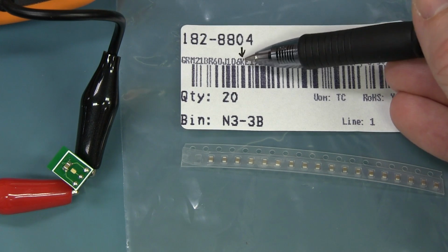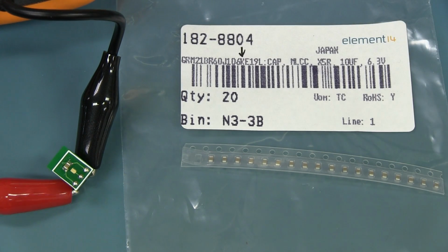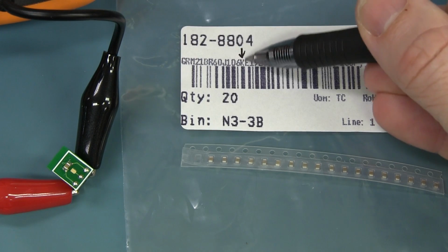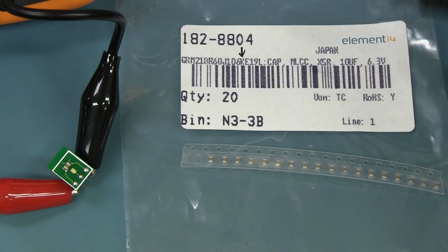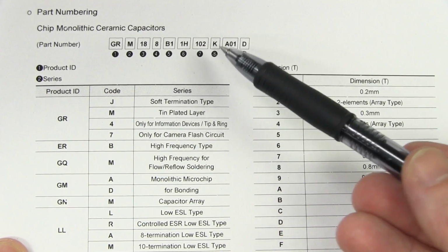Now, it's a nominal 10 microfarads with a tolerance defined by this letter here. In this case, it is K, and I'll show you the data sheet in a second. That is plus or minus 10%. Now, that's not the X7R. The X7R value of plus or minus, or X5R value of plus or minus 15% we saw before, that's its temperature coefficient change over that full temperature range. But this is the initial tolerance as you'll measure it and buy it from Murata straight out of the packet.